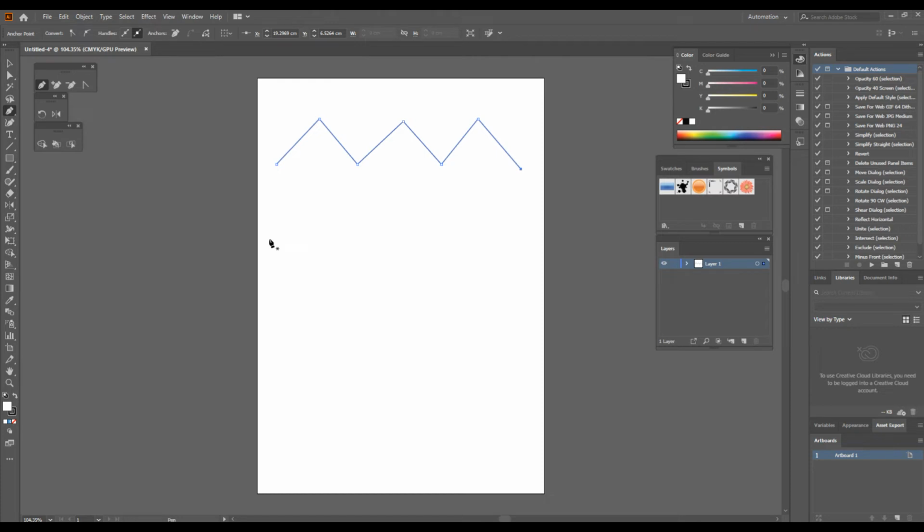And if you would like to create a curve, you can click to create a new anchor point. And when you create a second anchor point, this time you are going to keep pressing your mouse button. And if you move your mouse cursor, you can see the potential shape of the curve. And around the second anchor point, you can see two handles. Using this handle, you can control the shape of the curve. If you're happy, you can release.